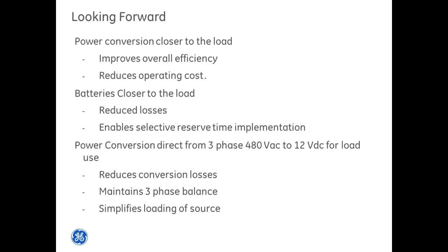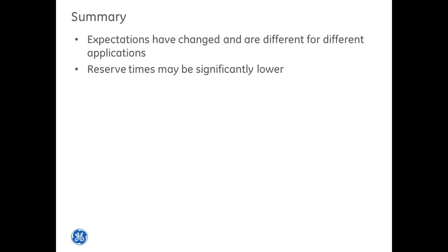In a lot of data centers, phase balancing is done manually. You have to remember when you add a load which phase of the AC you're going to add it to. So being able to do automatic phase balancing takes a lot of the manual effort out of adding loads. So it simplifies significantly the loading of your source.